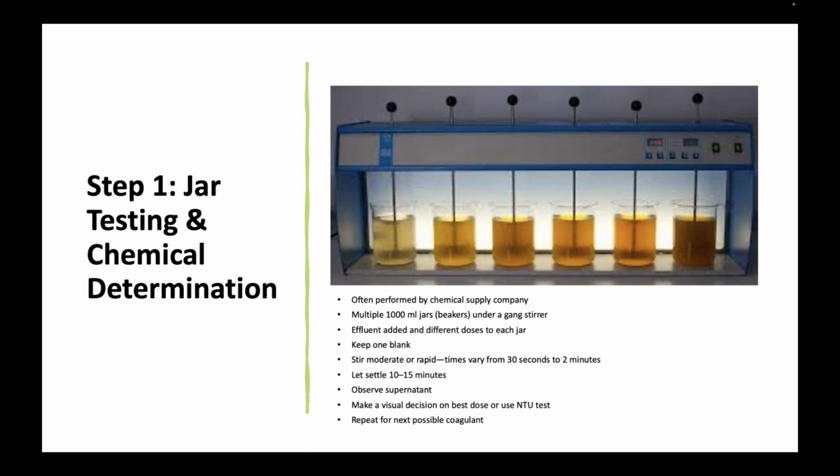One of the 4 that I mentioned or some other one, to see what works best, right? To see what can get the phosphorus levels down to your target requirement, to see cost, things like this, how much you have to dose in order to achieve that target, because everybody's wastewater is a little bit different. And so with these chemicals, I don't think there's an easy way to pinpoint one chemical for each application. You really need to do this jar testing to ensure that you get the right chemical.